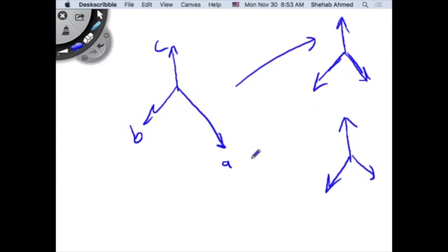It will have the same sequence, right? If you're standing here, these are phases. They're rotating with time, right? They're actually changing with time. This is a frequency. They have frequency content there. If you're standing here, you will see A first, then B, then C, right? And this is called the sequence of that voltage supply. So let's say we will call this positive sequence. So an observer will stand here, will see phase A, phase B, and phase C. Same thing, if you're measuring, you will see phase A first, then phase B, and phase C. That's positive sequence.